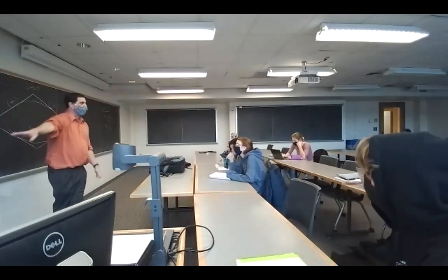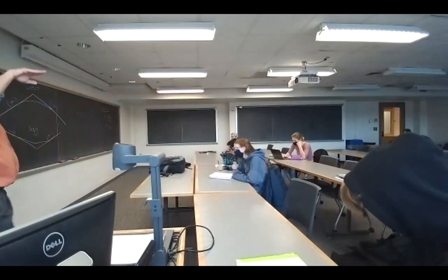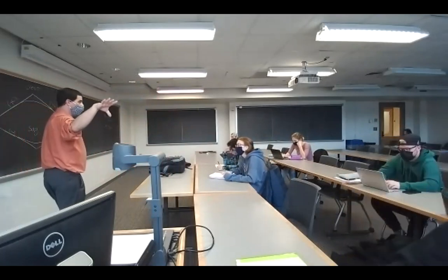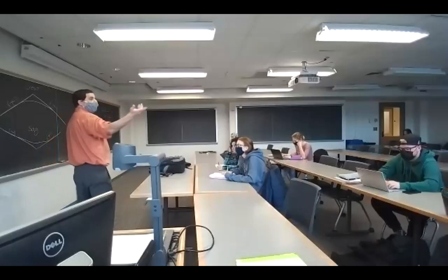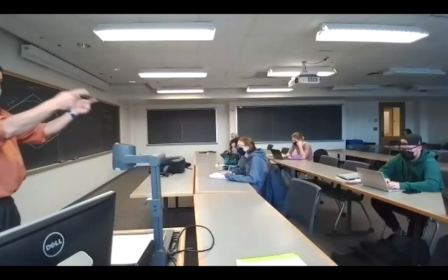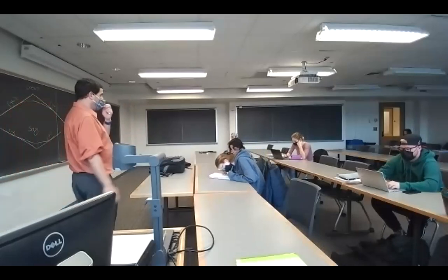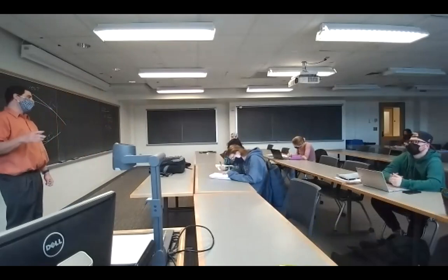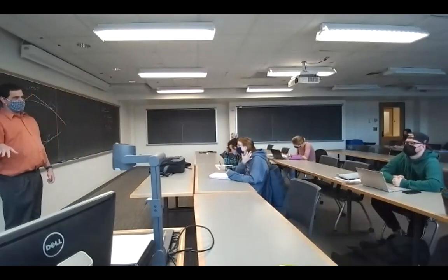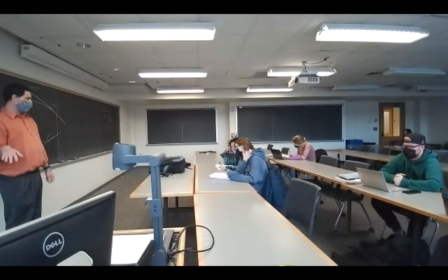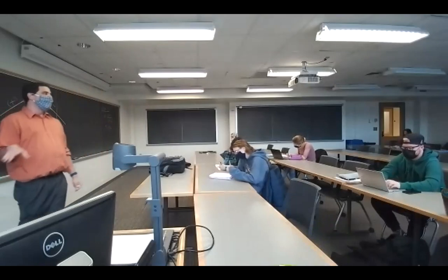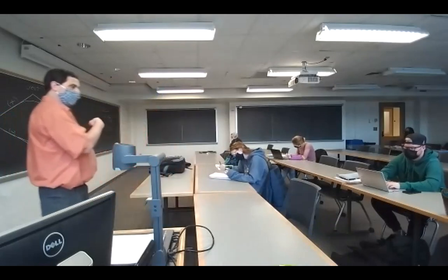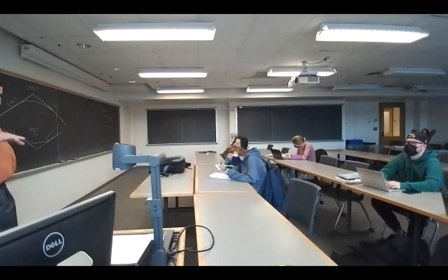this isn't in the textbook. Your eye height is typically calculated at, what would you think? It's actually 3.5 feet. So, yep, bang on. Is that right for most vehicles today? Probably closer to 4 for most vehicles today because SUVs and pickups tend to be a bit more common. Passenger cars, you're closer to 3.5. But for the purpose of the calculations, most DOTs use 3.5 feet.